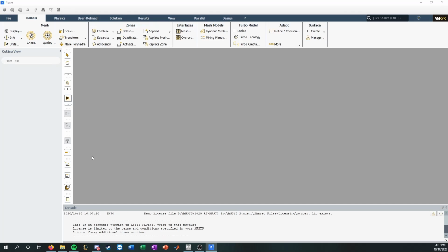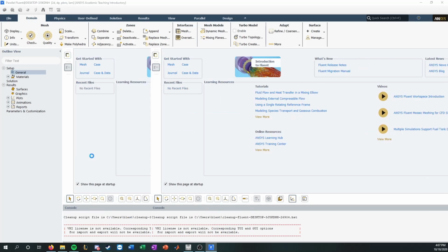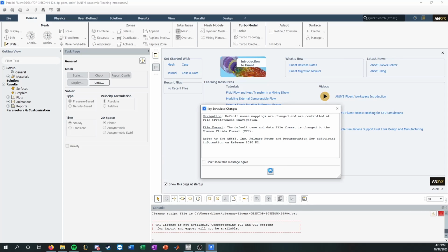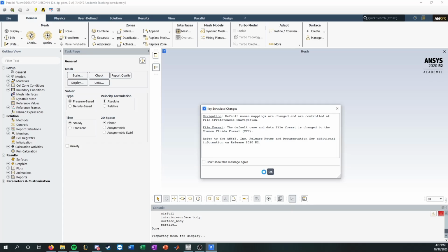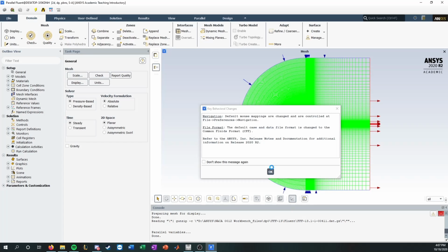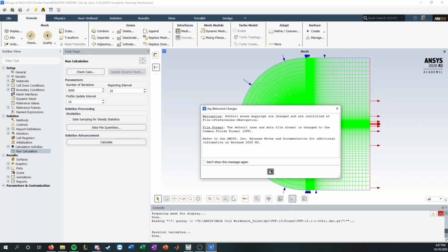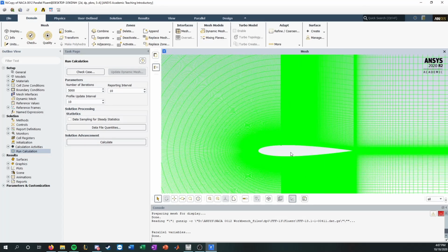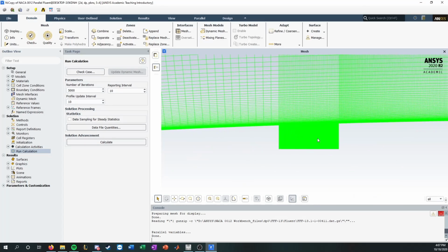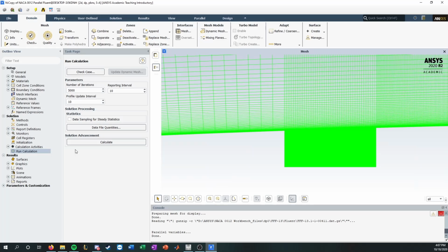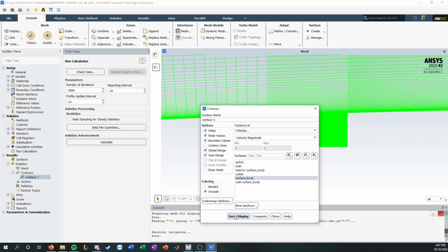Curved dimples are very hard to mesh in ANSYS Mesher. So I would highly recommend, you can take my word or you can put in the hours to realize it yourself, but it's pretty hard to mesh a curved part because, as I mentioned, you definitely likely cannot face mesh it. And I actually spent probably an hour trying to do one like that, and I ran into issues. So this is a similar one where instead I have a region here. And what I actually saw, it wasn't as bad as the other one.